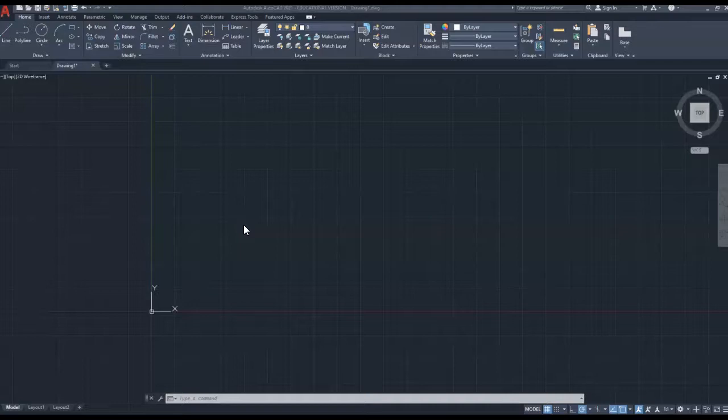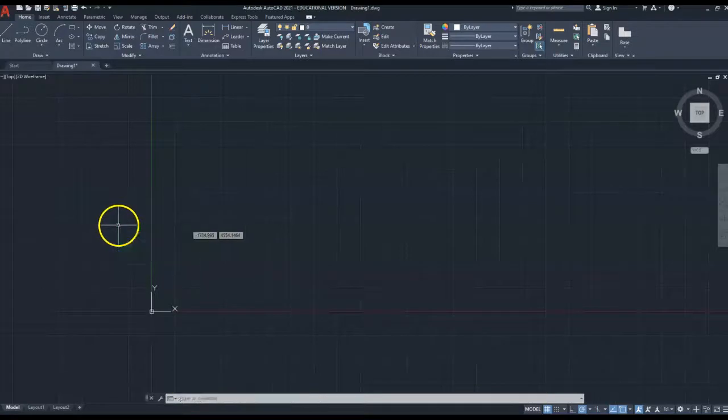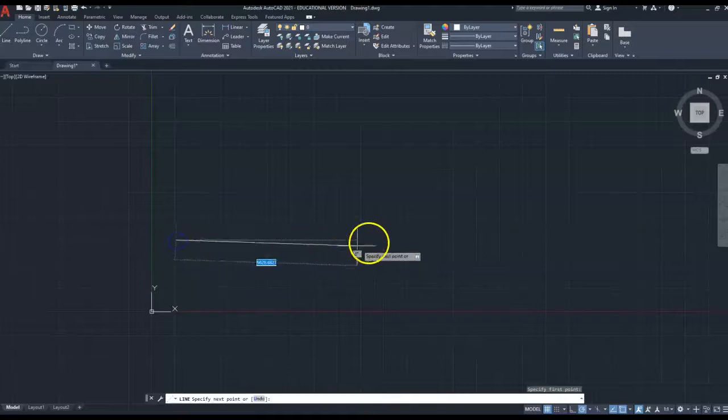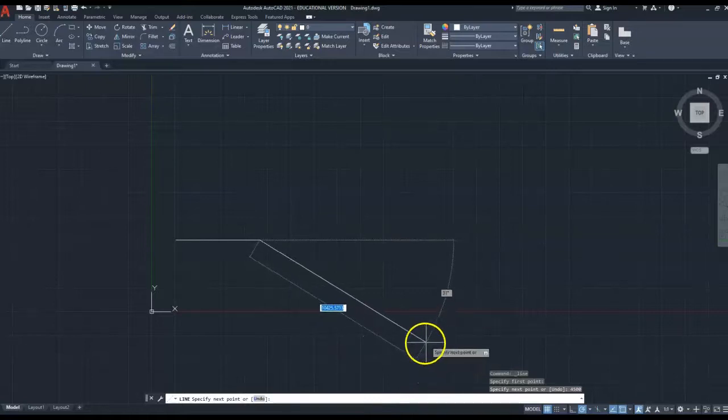So I'm going to go through that process on the basis of a normal semi-detached house using standard sizes. I'm ready to start drawing, so I'll click line to draw, and the standard width of a house is around 4.5 meters. Oh, I haven't got draw. Just click escape, make sure that I click the line so I can draw. There we go. So standard width is 4.5 meters, so that's 4500, and return, and that gives me my line.